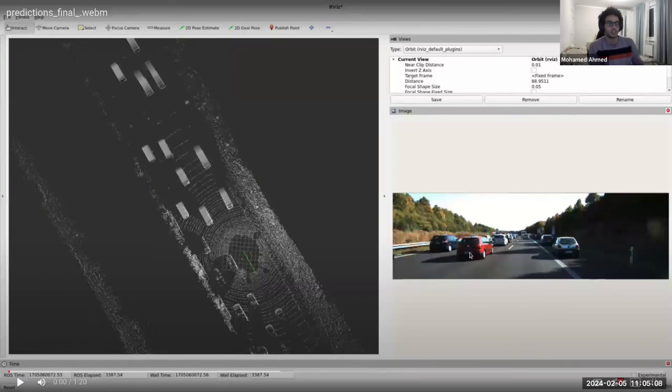However, you need to take care about the resolution of your camera. For example, if your camera is working with 60 frames per second and each image has a very high resolution and it's sending 8 megapixels, then this can be an overhead for your bus, and maybe you need a fast network. This is one of the problems that we dealt with before. However, ROS can provide any speed you want. You just need to take care that your hardware supports this speed.